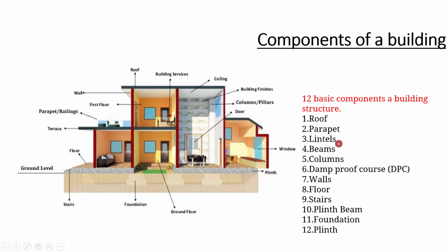So what is a lintel? You can see a window here, and I told you the wall will be a load carrying member in the case of single-story or two-story buildings based on the design. As the load from the roof is transferred through the walls to the foundation, when a window or door is made, there is a discontinuity in the load transfer.